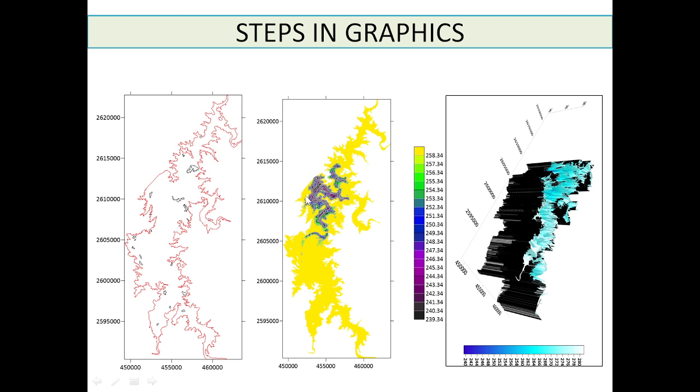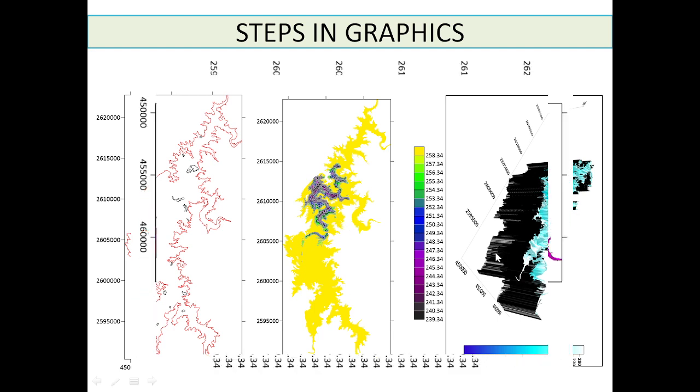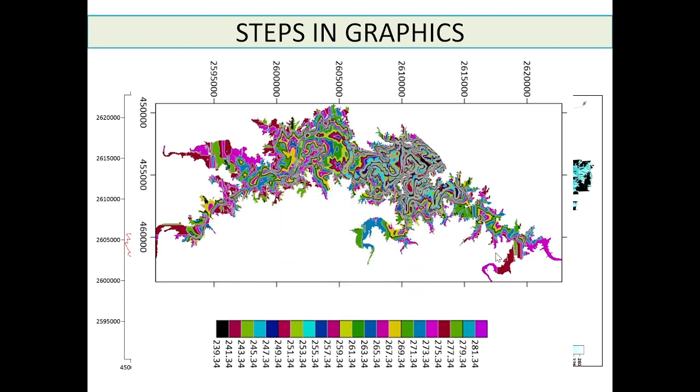Then we created this particular project for the Nuclear Power Corporation. They wanted to understand the deep pockets and then lay a pipeline. The power plant is coming at this particular area. So the deep zone is here. Overlaying a DEM over this will give you the dam and the land elevation, so you can guide them on the pipeline route. In between there are some hillocks, so you can bypass them and then bring it to this. And then this is a 3D plot. Yeah, so this type of output is very useful for them in deciding. This is a 1 meter contour.